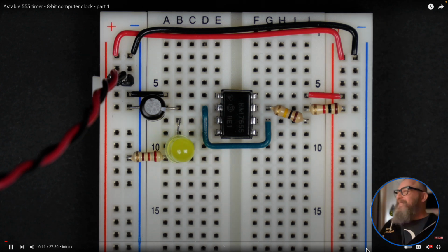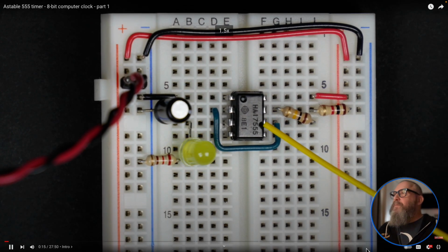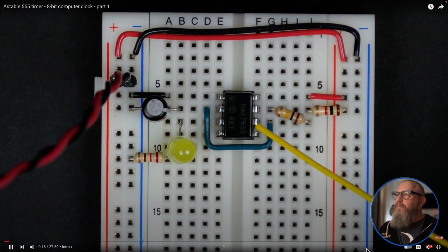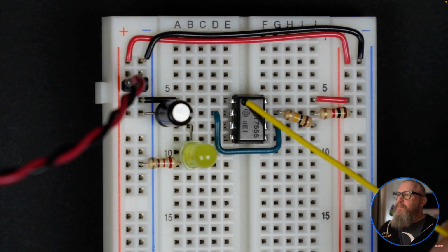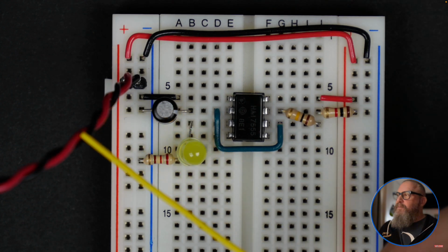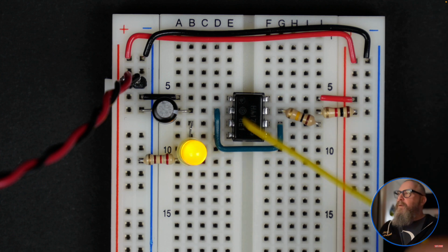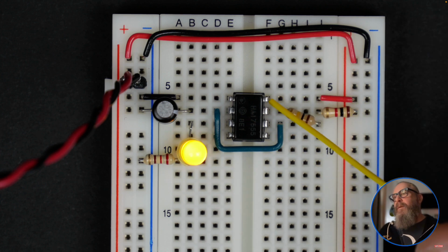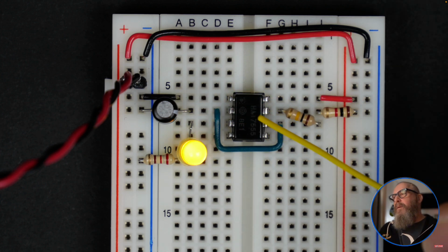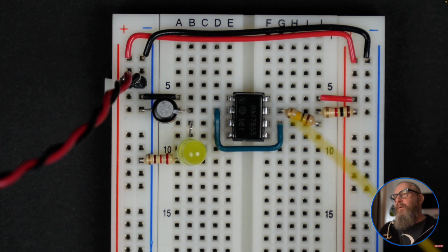And so I'm going to use the 555 timer. This is a classic integrated circuit, and that's what this chip is here. You can tell pin 1 by the divot, and then 1, 2, 3, 4, 5, 6, 7, 8. Right now I'm powering this with 5 volts coming in from a cell phone charger that I've cut into the USB cable and pulled the 5 volts out of. Power comes in at 5 volts on pin 8, and ground goes to pin 1. You can actually go up to, I think, 16 or 17 volts with this chip, but 5 volts works. To control the timing, you've got 2 resistors and a capacitor.